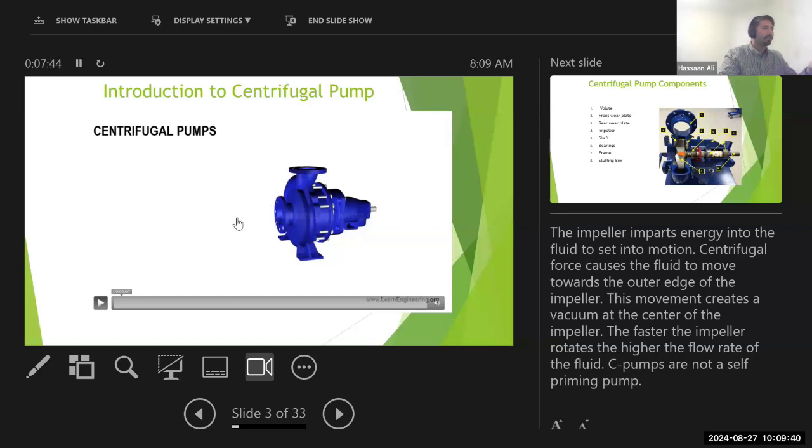And the third type of pump is called positive displacement pumps. These are your rod pumps, your beam pumps, your diaphragm pumps, your high pressure rotating pumps. And those are a different type of pumps that are used in the industry. Now, industry has a manner of selecting which pump is suitable for different applications. Usually centrifugal pumps are required when there is low to medium pressure applications, but if we have to go for a high pressure and low flow application, then positive displacement pumps are more suitable.